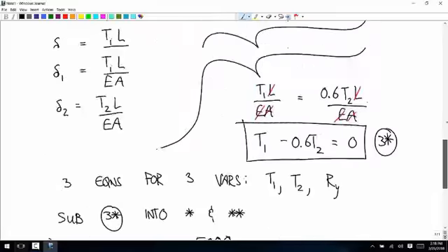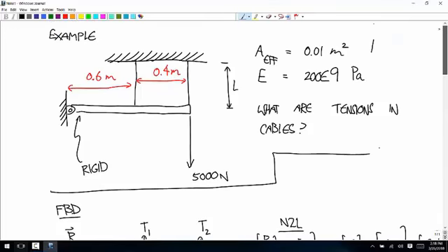Okay, so what we got is, because of the positions of these two cables, which one is closer to the end, which one is closer to the hinge, even though they're the same material and the same area, most of the force is going to be taken up by this cable at the end. Less is going to be taken up by that one. And that's because as this thing deforms in a straight line down like this, one is always being forced to stretch more than this one.